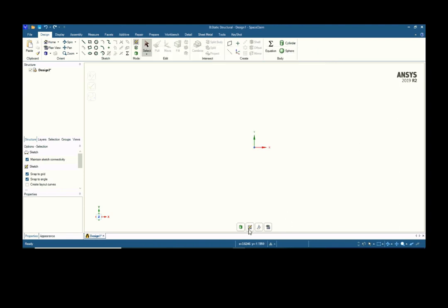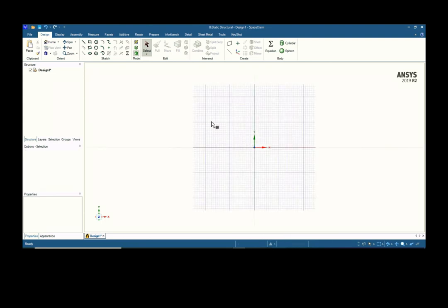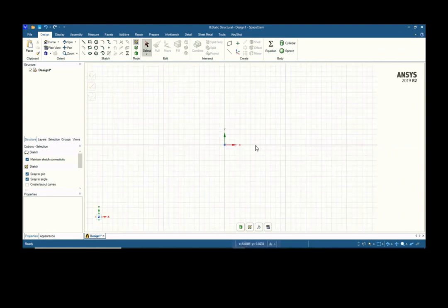So we need to call out the grids. What we need to do is click on this, so we click the grid itself, so that we create just now the new sketch plane, which is the XY plane now. Then here come the grids. You will see when we zoom in, this is a major grid. Each major grid has 12 inches of minor grid: 1, 2, 3, 4, 5, 6, 7, 8, 9, 10, 11, 12. So this itself is 1 foot or 12 inches.